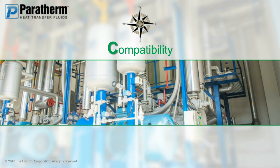One thing you need to be concerned about is copper is usually a tricky one. If it's on a heated surface, there's the heat source behind that copper on the other side of the fluid. That can be a catalyst for oxidation. So whenever copper is present in your system, make sure that you take the extra step of considering that compatibility with the fluid. Talk to the suppliers that you're looking at.